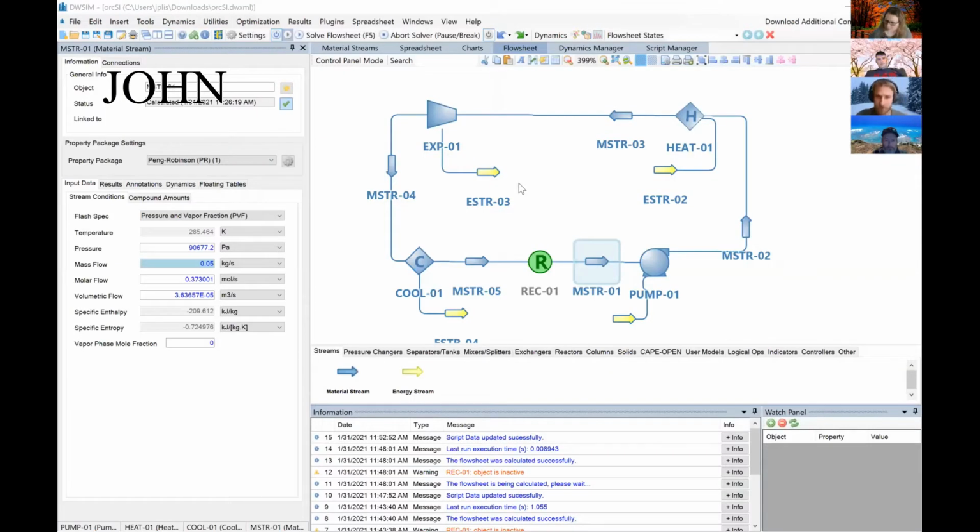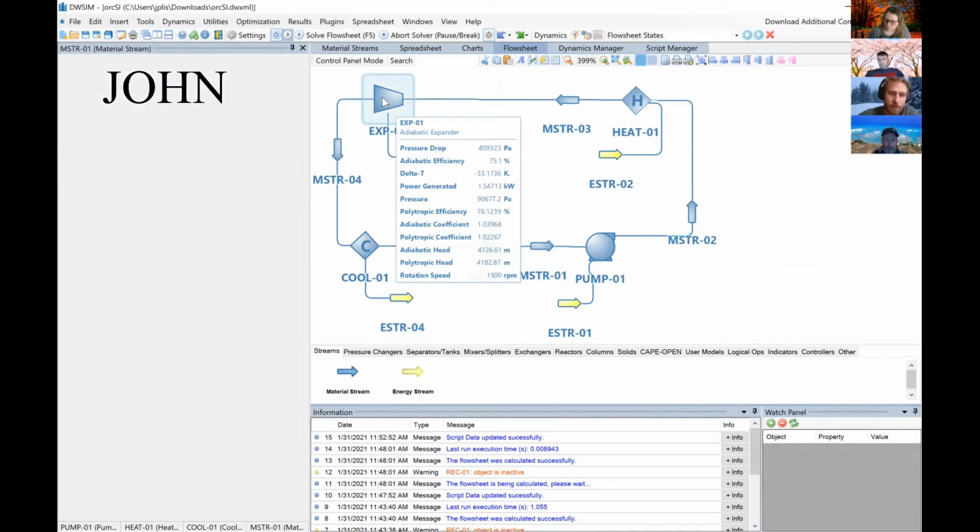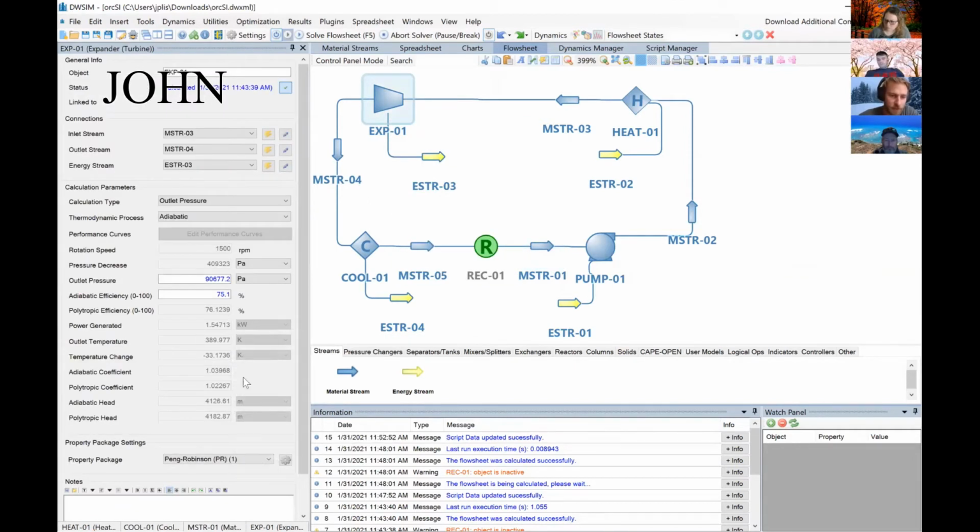I'm going to walk you through some of the simulation updates that we have. This is the DW simulation software on your screen, and this is a very bare bones model of our organic Rankine cycle. This will be our fluid, our pump, our boiler, and our condenser, and there's our turbine. From this, we can set up our mass flow rate and see, as we increase that, the kind of wattage that we'd expect to see on the outtake.